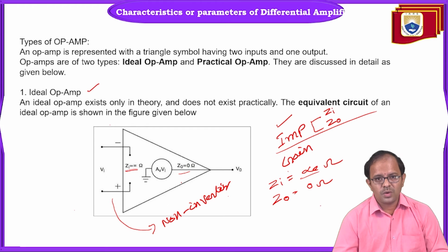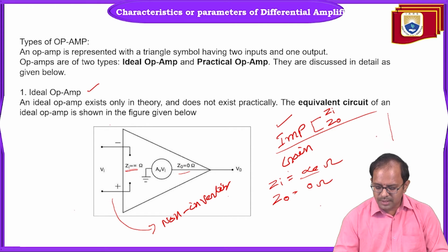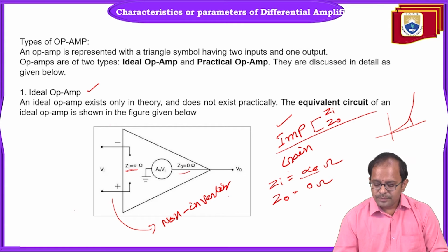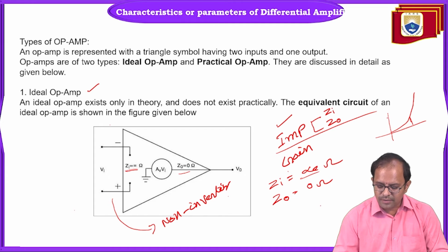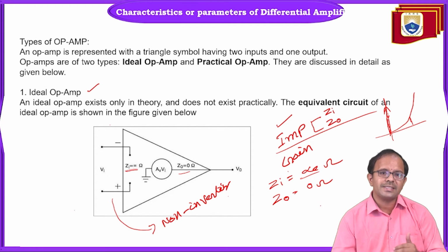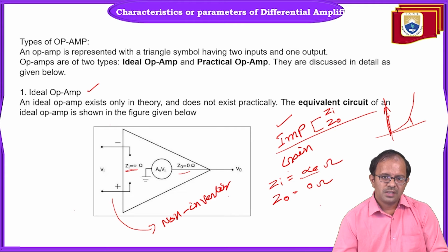And even in the case of a diode, the VI characteristics, if you remember, seem to be like this. It is gradually increasing after the cut-in voltage, 0.3 or 0.7, depending on the material, germanium or silicon. This is for the practical scenario. And in the ideal case, we will say that the current starts increasing instantaneously the moment you start increasing the supply from 0; a fractional increment in the voltage is sufficient to see the current in the diode. That is the ideal case.